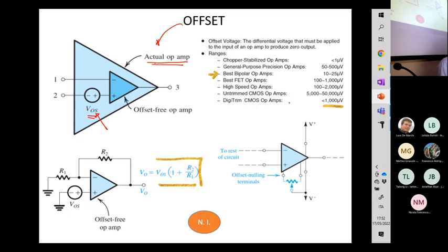We have discussed the offset of CMOS op-amps, and as you see, this quantity can be quite relevant, from 5 millivolts up to 50 millivolts. If you trim the op-amp somehow to compensate for the offset, you can get lower values.